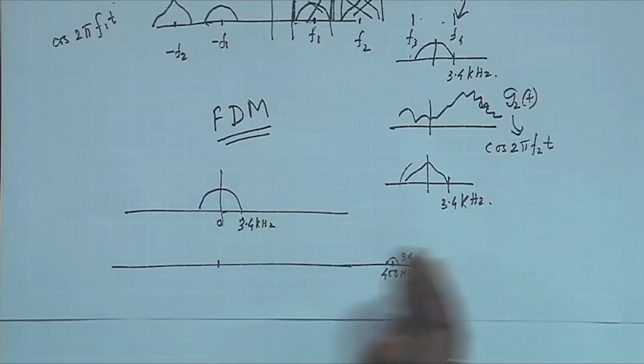So, it is very much essential that the frequency is higher to facilitate the antenna size being smaller. With modulation we are also achieving that, because if you see, very small frequency components will have huge wavelength, since it is inversely proportional, and the antenna size will become very huge. Whereas, by this simple technique of multiplying the signal with a cos, it serves two purposes. One is it translates the signal to a very high frequency, so the corresponding wavelength will be much smaller. So, I can devise a very small antenna for my transmitter and receiver.